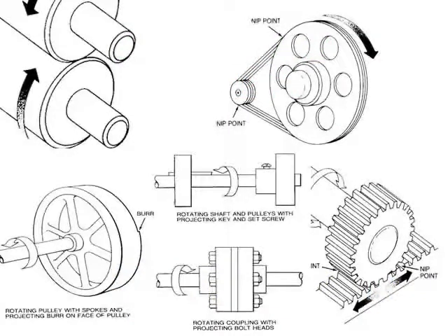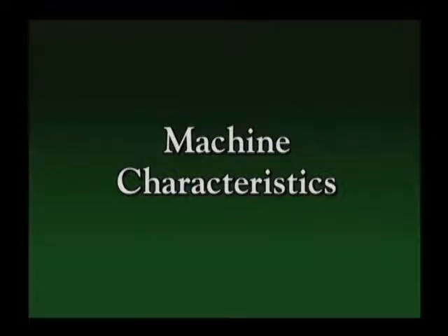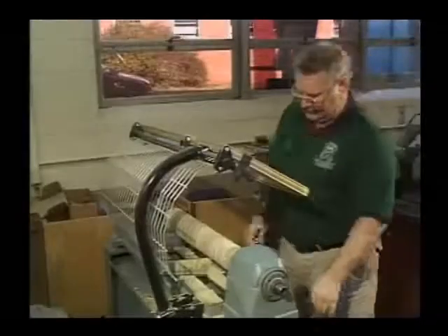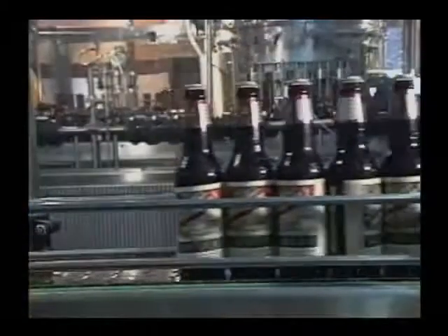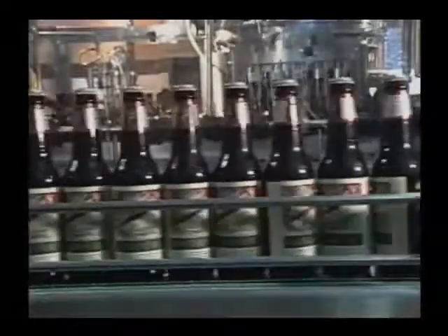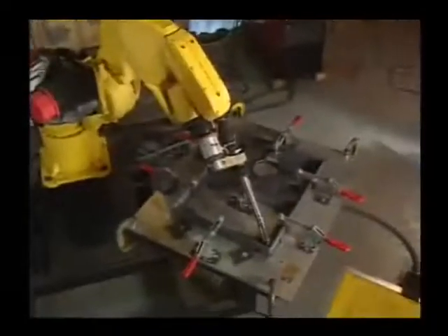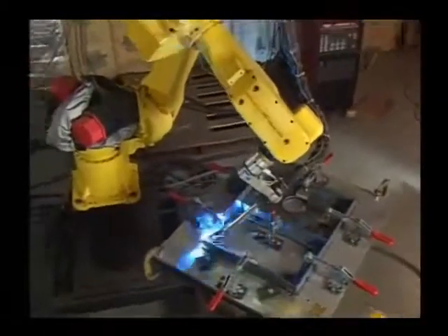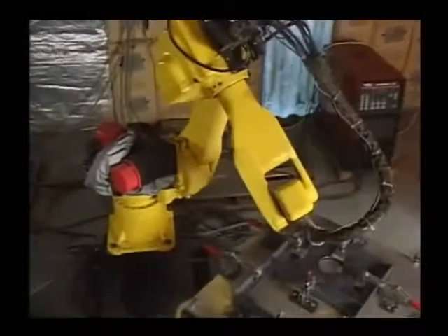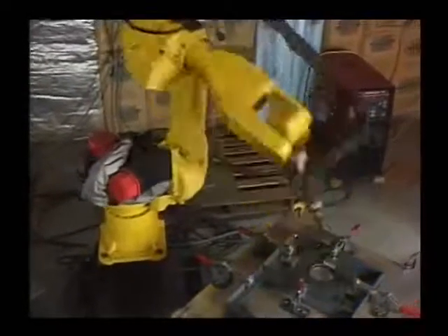This will help us to identify potential hazards and understand how machinery guards and safety devices can be used to contain them. All machinery operates using a combination of three basic motions. So, rotation, reciprocation, moving back and forth, and transverse motion, moving in a straight line. When these motions are combined, they produce what is known as articulated motion. And this can be especially dangerous because articulated motion makes it hard to predict which way the machine parts will move.